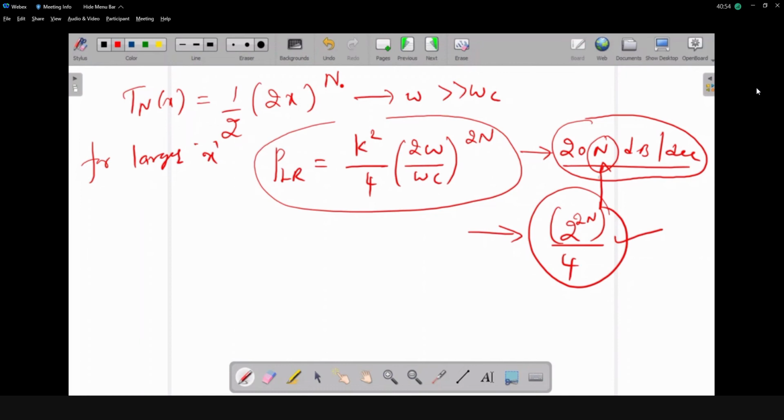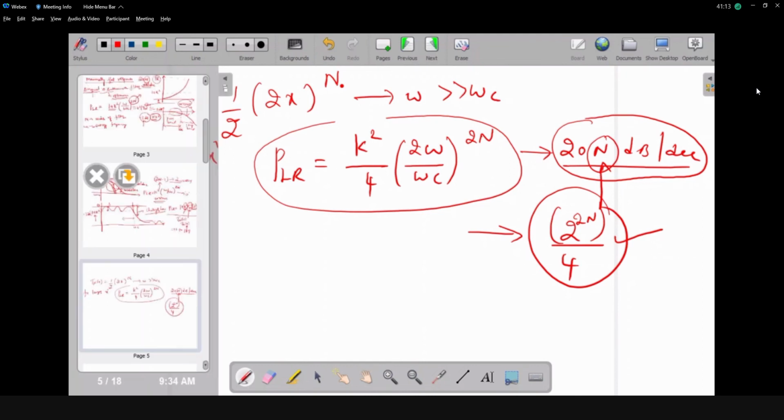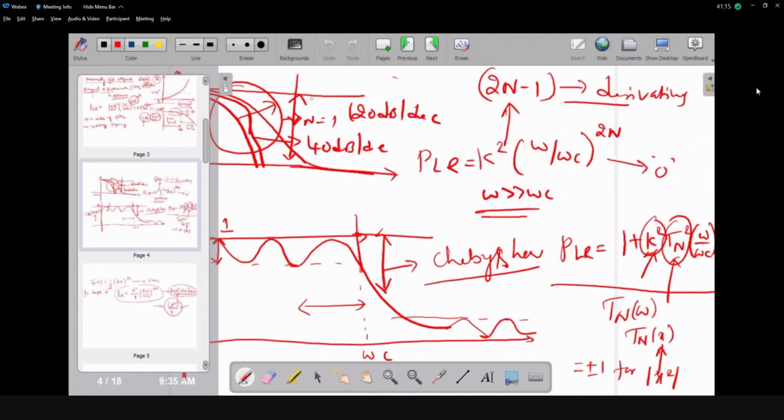Now this is about the equal ripple response, and then we have another function, the elliptic function, which we discussed earlier. The maximally flat and the equal ripple or Chebyshev responses both have monotonically increasing attenuation. You can see here that both are increasing with respect to this 0 dB level. Monotonically, the insertion loss keeps increasing, from the 0 dB level and also in the stop band.